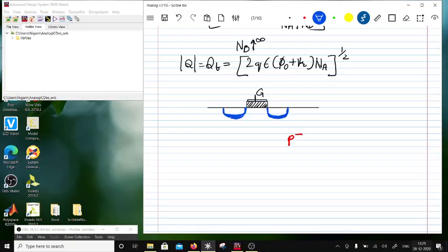So you have this portion which I am going to call N plus, and these terminals are interchangeable. They are source and the drain. And besides that, there is another terminal which will be P plus, and then you will be interfacing this contact, which is the body.